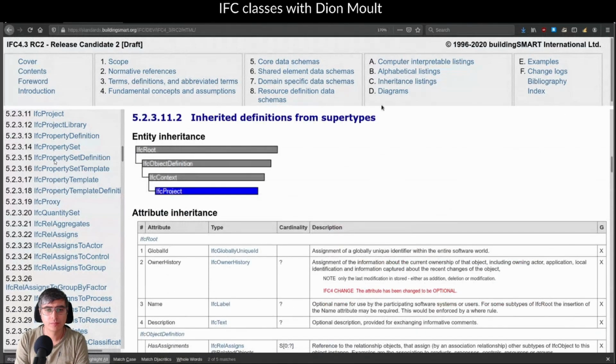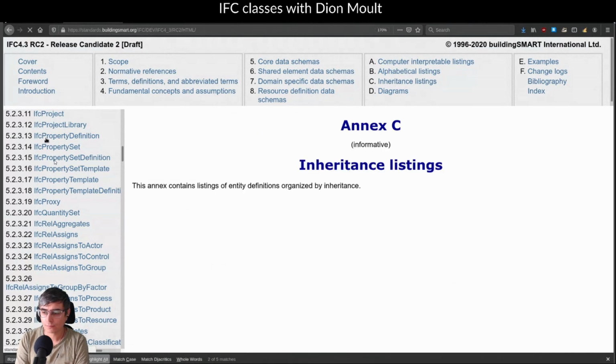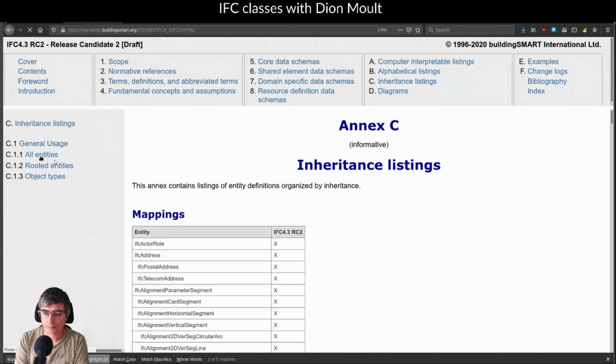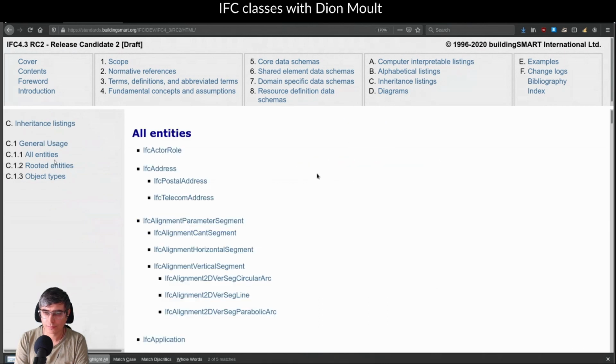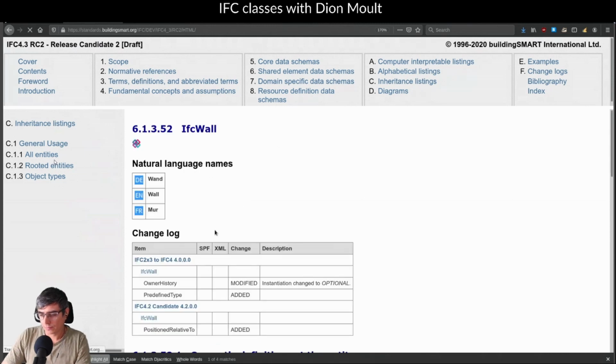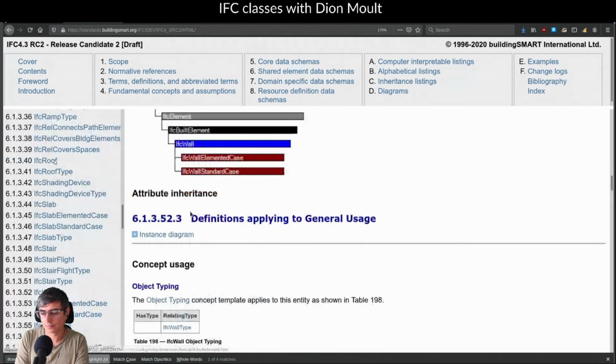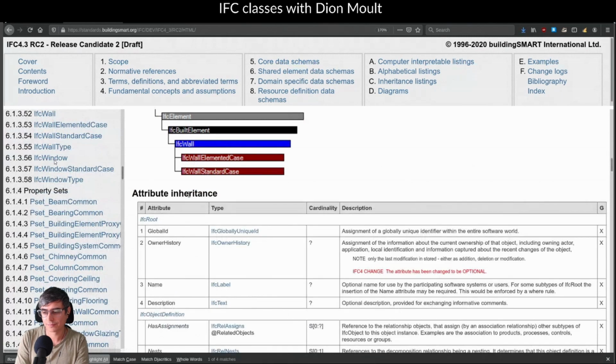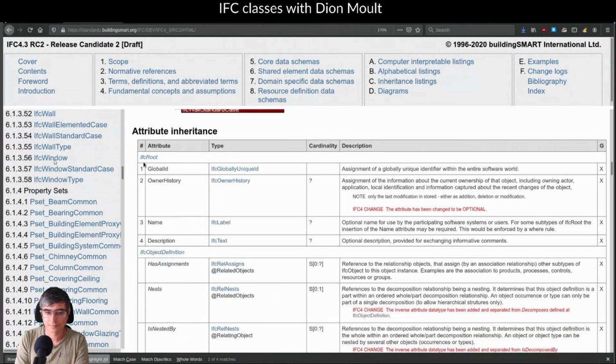So you will actually need to click on all those complicated links that I clicked here and find a particular object that you're interested in, let's say a wall. Let's say you want to know what attributes you can give to a wall. Then you can go down to attributes. You have to click this because it's hidden by default. I know it's all confusing and terrible. And then you have to say, okay, name.